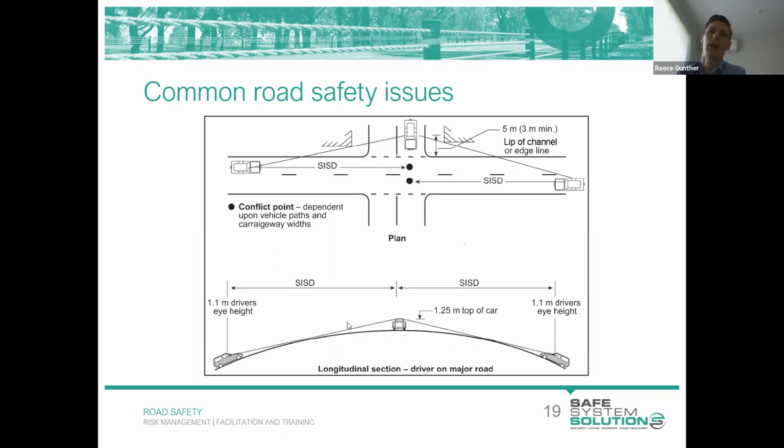When we're looking at the vertical sense, we've got the same intersection, but we've cut a profile along the road. We're at a crest, or the intersection is a crest I'm seeing here. For the motorists traveling along, it's measured from the driver's eye height to the top of the vehicle. Now, if the crest was short and sharp, and that line there was being impeded by the crest, we would have to look at a number of treatments to adopt.